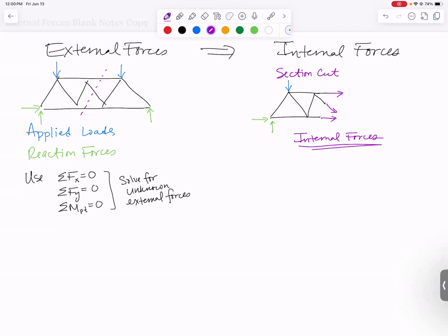Okay, and you've used those before in statics. You've seen those internal forces in a truss when you cut open a section. You've also seen those internal forces in trusses when you did a joint diagram. So let's say I take that joint right there and I want to do a joint diagram. Here is my joint, and it still has an external force applied to it, the blue downward force. But now on that joint diagram, you can think of it as you've removed those three members or you've cut them open. And what they end up doing is applying tension or compression to that joint. Those orange ones are also internal forces.